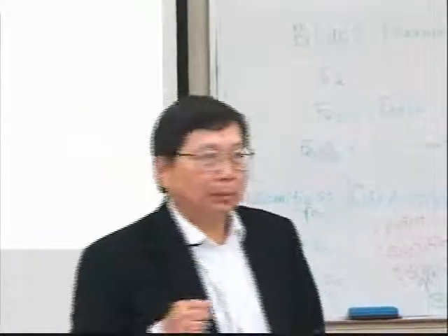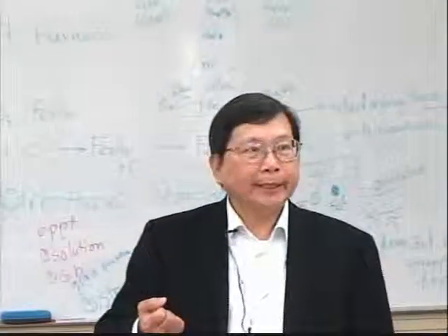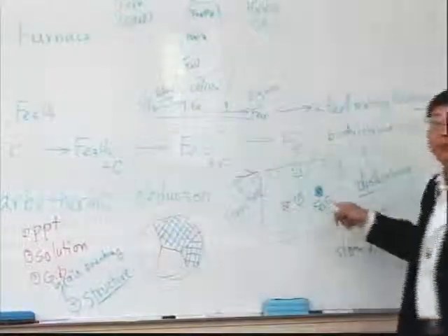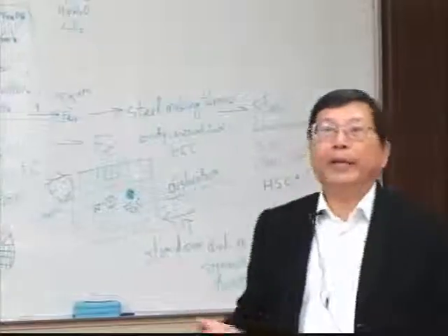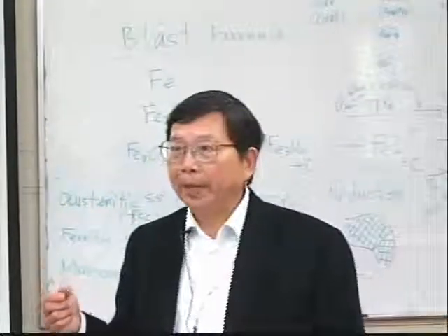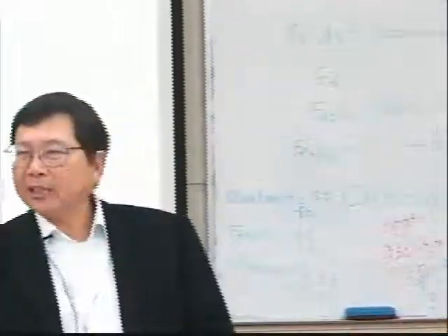It's called heat treatment. What is the purpose of heat treatment? Well, heat treatment is to create precipitation, to create different kinds of precipitation. So like aluminum, one grade of aluminum is called 2024 aluminum alloy. Okay, another grade is called 6061 aluminum alloy. Typically, the higher the number, the stronger that aluminum alloy.